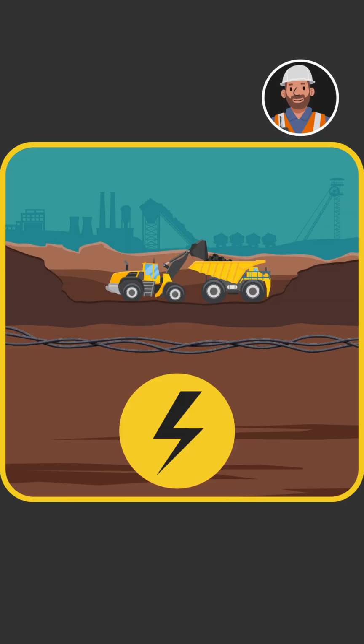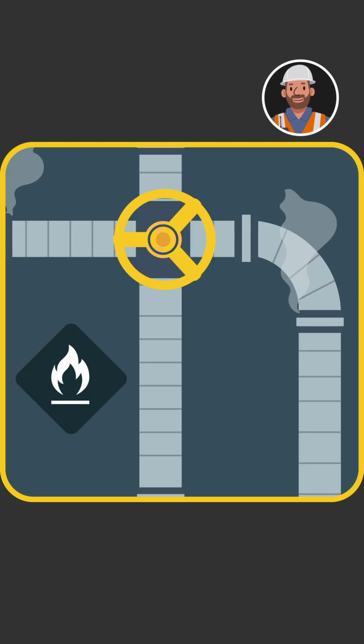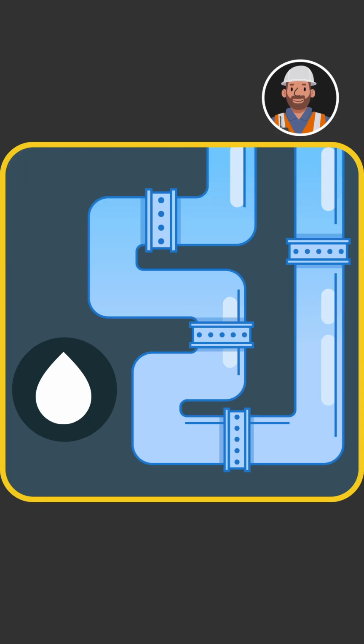Electric cables. Electricity can arc over small distances, and crushing cables can break their insulation. Gas mains. Damage can cause fire, explosions, or asphyxiation in confined spaces. Water pipes. High-pressure water jets can harm people, create projectiles, and flooding can destabilize the ground. Even if injuries don't occur, there may be heavy fines or repair bills from utility companies.